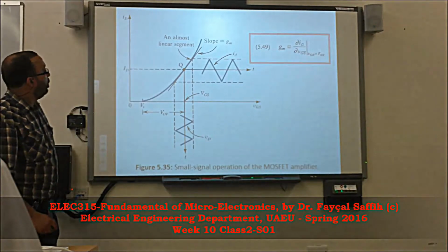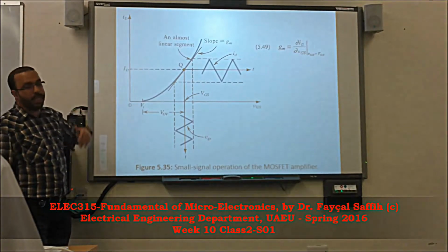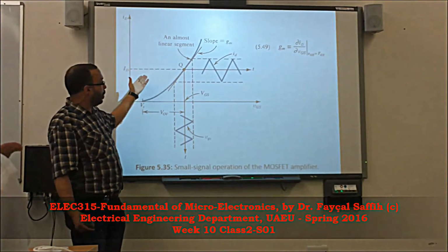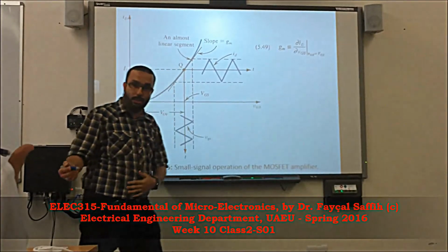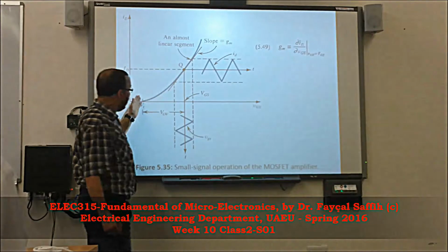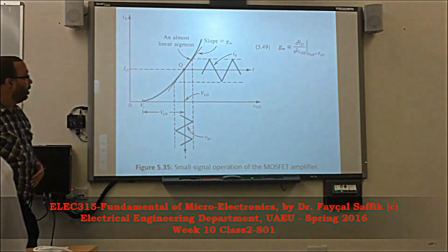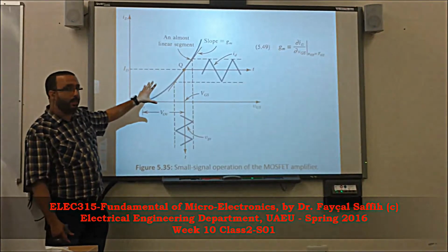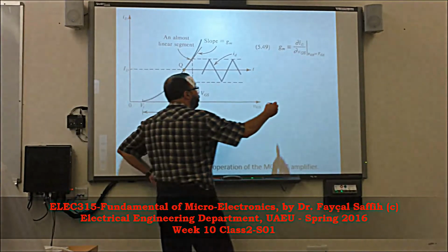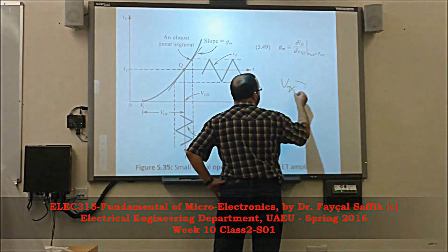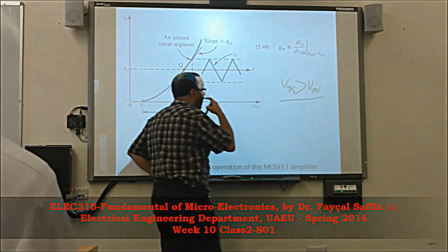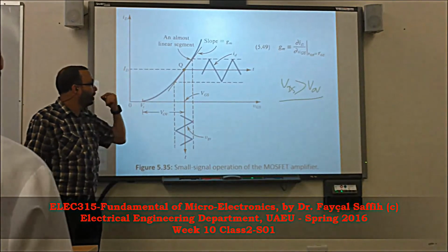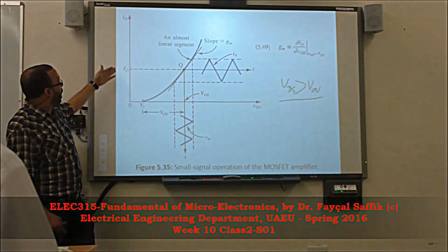So drawing the curve of ID versus VGS that we saw last time, it starts at VT and goes up. Is it exponential or quadratic? Remember, here we have to make sure that we are in saturation, which means we must have the condition that VDS is bigger than the overdrive. Because the picture only relates ID with VGS. So if VDS is above the overdrive, we have this relationship.